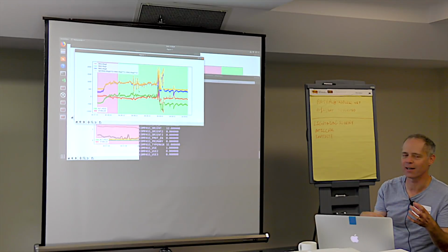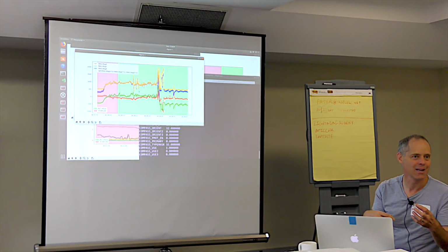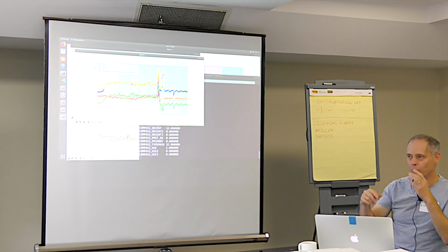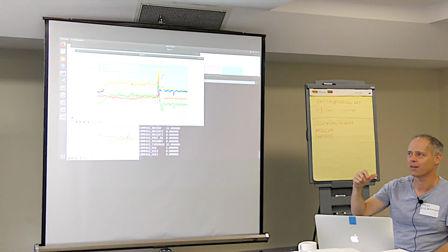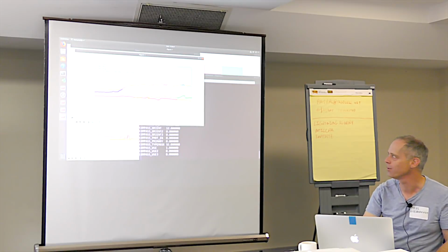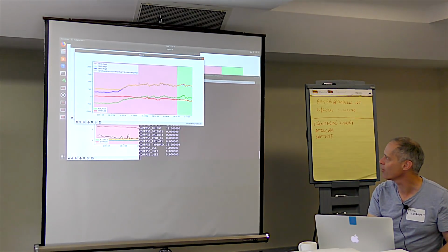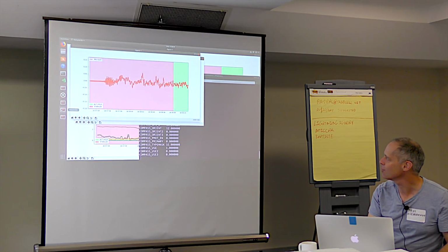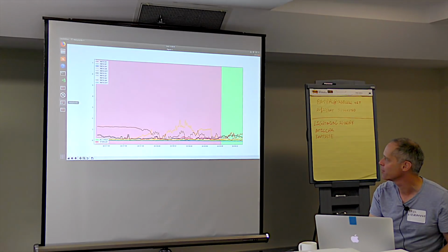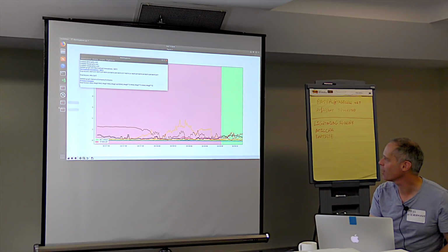So what do they do to make one magnetometer, one magnetometer was failing on the ground, right? And then it started to pass, and then the other one was passing, and then it started to fail, right? Well, one EKF was failing and then passed, the other one was passing and then failed, rejecting the magnetometer. And it happened at a particular point in time, and it's got nothing to do with your rotation, but there was an event. There has to be something that's changed. What changed? They did a takeoff.